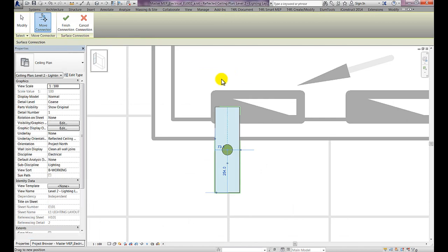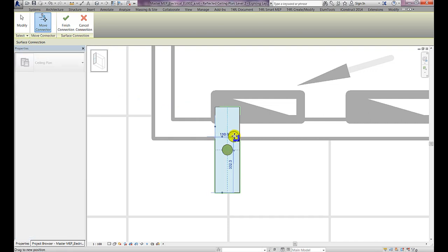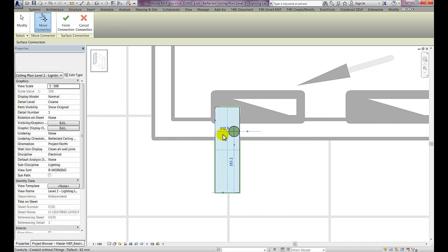The conduit connection mode is activated and you are presented with an elevation view of the side of the panel, along with a small 3D view for helping you orientate and show you roughly where the conduit connection is in relation to the side of the panel. The location of the conduit connection can be adjusted by clicking and dragging, or by using the temporary running dimensions to place a specific distance from the edge of the panel.